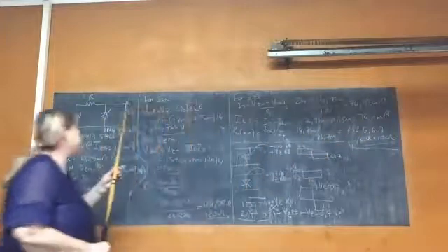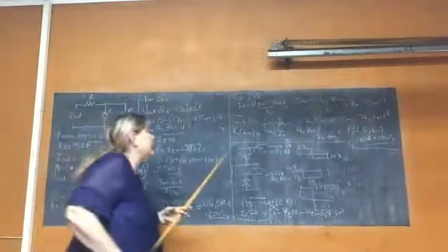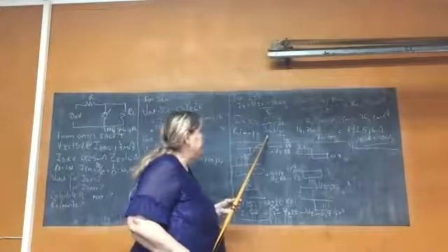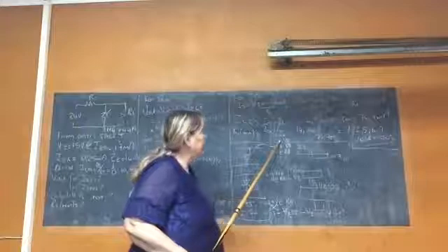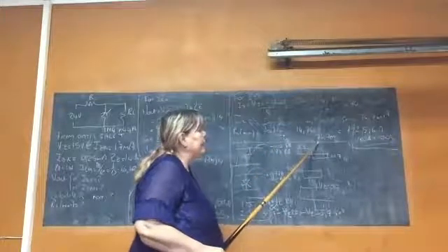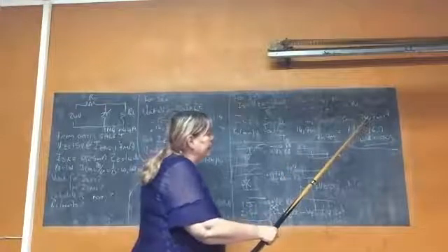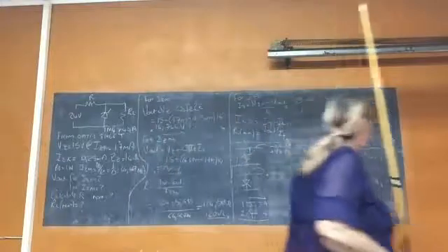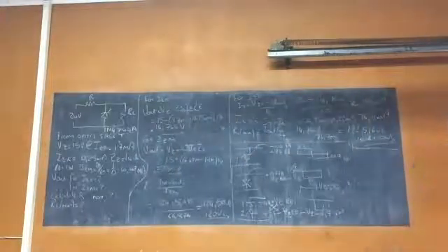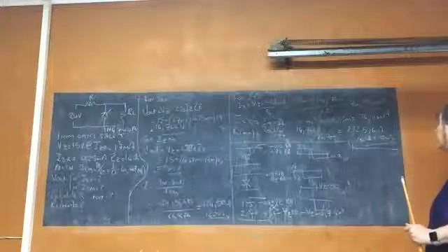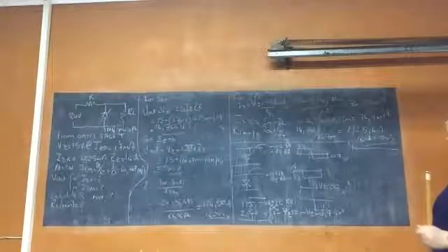Now, if you have the current through the load, you can determine the minimum RL. It's V out over IL. It's 14.766 over this current, and you get a number of 1925, 1K925.